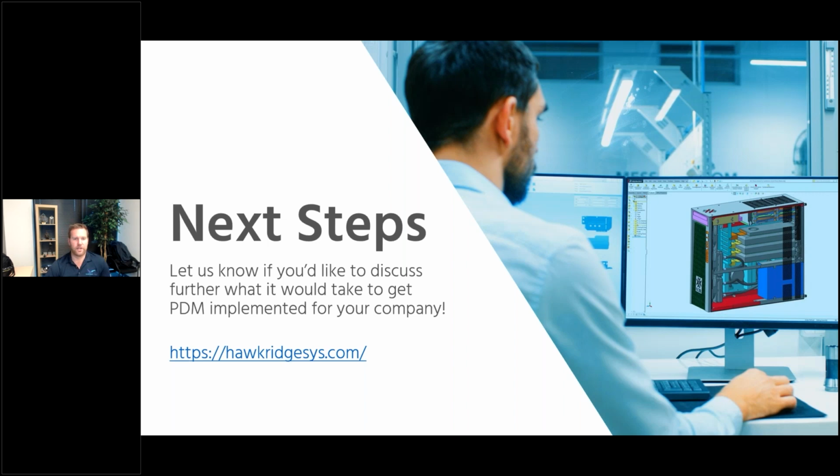Alex, your question, really good one. Can the metadata be changed by a non-SOLIDWORKS user if desired? For example, could a purchaser update the price of a purchased part? The metadata can be changed by a non-SOLIDWORKS user. They would have to have access to the vault, which would consume a license, and the vault resides on a network. So as long as they can get access to the vault and they have permissions, yes, definitely outside users or non-SOLIDWORKS users could update that metadata.